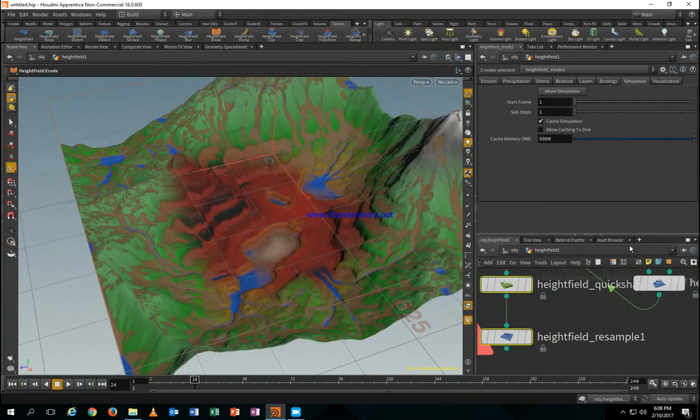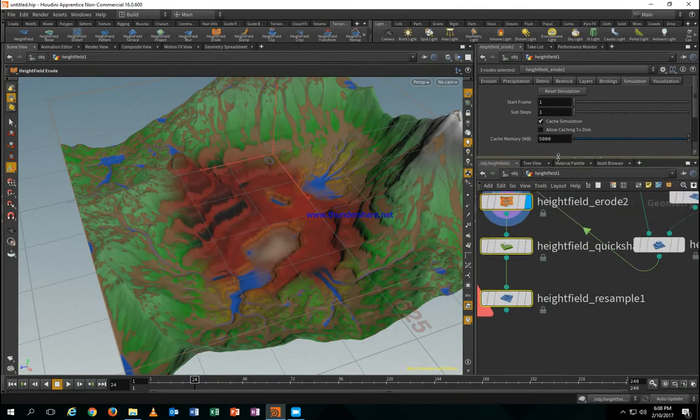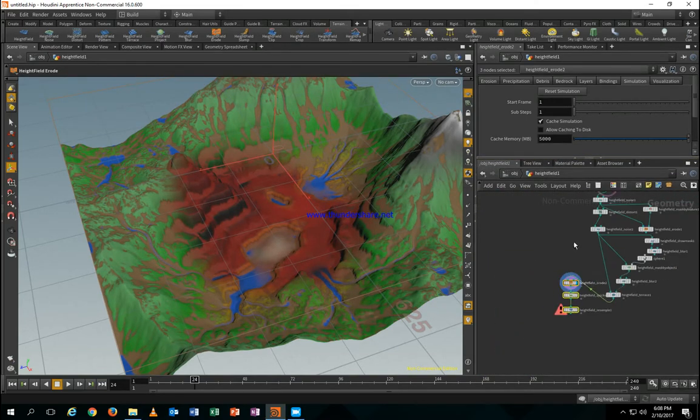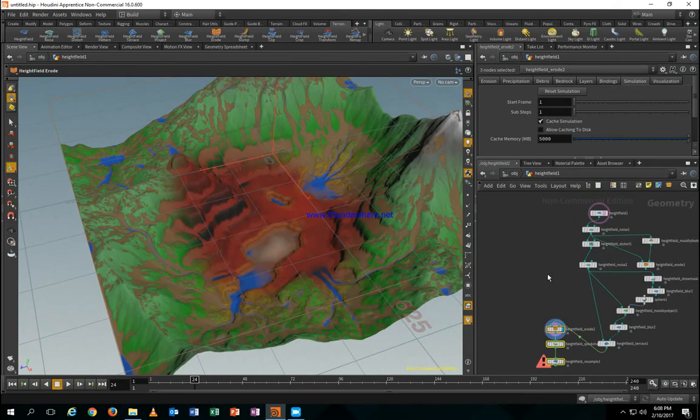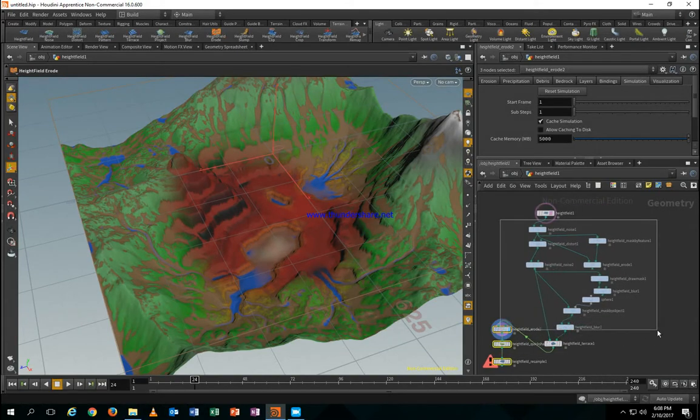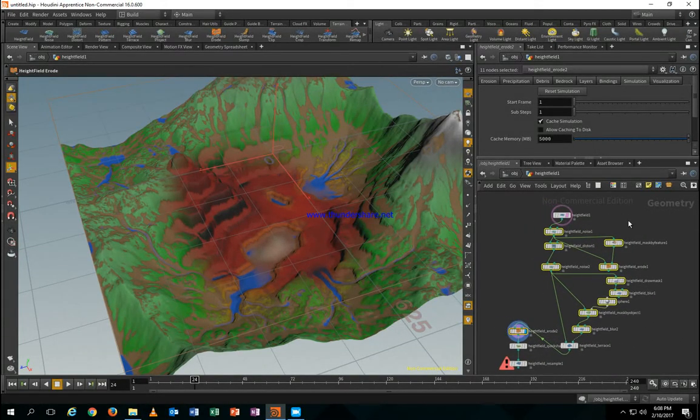Yeah, that's it. So the way a pipeline for the terrain building works is to start with adding noises. You can group them together. So it's actually just building up layer by layer. You build up your debris and then water layer, and then bring them together using HeightField layering and resampling at some point. You can paint masks. You can mask based on features.